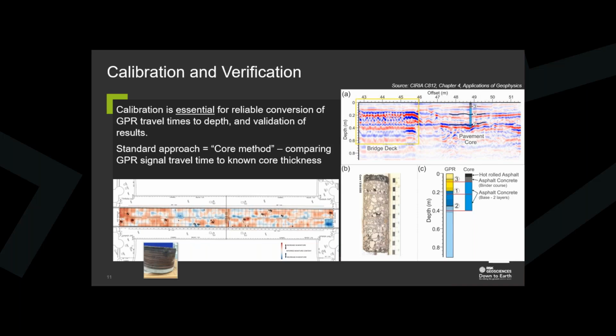So for example, if you know your GPR profile is going to be 1 kilometer long, you'd probably want to calibrate your survey wheel over at least 100 meters for best accuracy. Then you simply drive that 100 meters along the tape measure, tell it when to start, tell it when to stop, and then it will have a value of how many ticks the odometer wheel will output, and that can be used to make sure that it's transmitting at the correct rate. So by doing that, you're making sure that the position along the road of your data is accurate and well known.